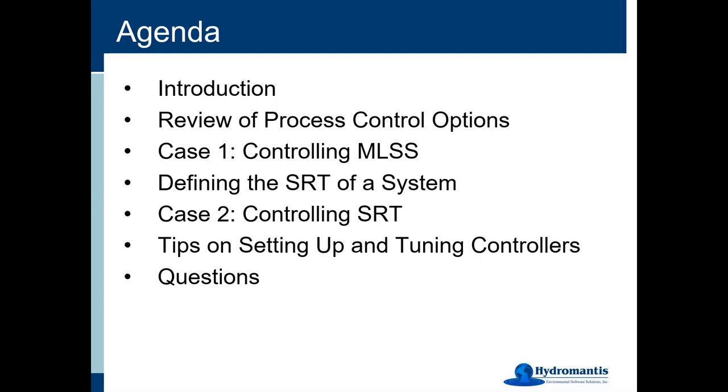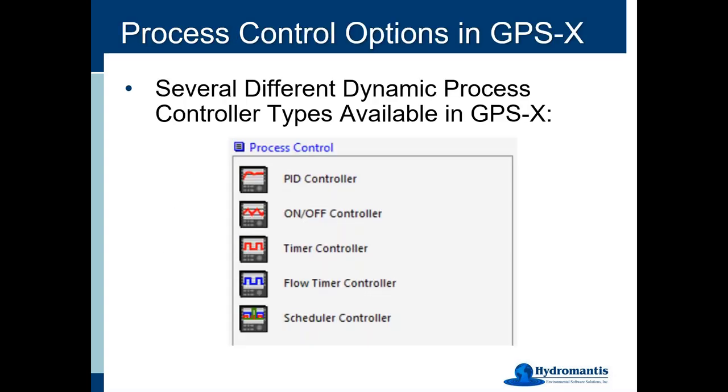Then we'll talk about how to set up a PID loop for controlling mixed liquor, and then we'll go into how to define an SRT and then apply a controller to that as well. And then I'll wind up with a few typical tips and things that you should keep in mind when you're putting your model and your controller together, and how to troubleshoot when you have any problems. And then we'll answer those questions that you've typed into the box when we get to the end.